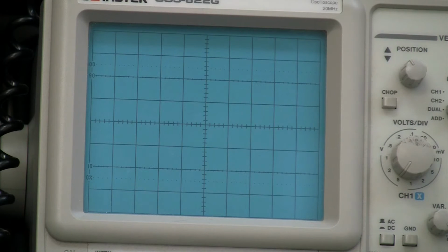Now, remember we are running through a clipper, and I have the clip level set to 10, so that may be what's causing that clipping up there. But eventually you will hit the rails, and when you do, you won't be able to get the signal to go more positive. You'll hit that somewhere between 13 and 14 volts. At this point, I only have the control level turned up to 5 on the Q108 amplifier, while the gain knob is set to 10.